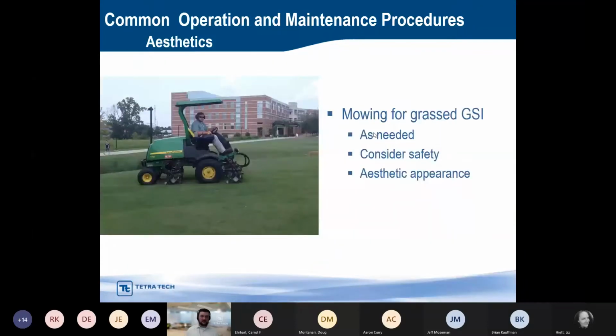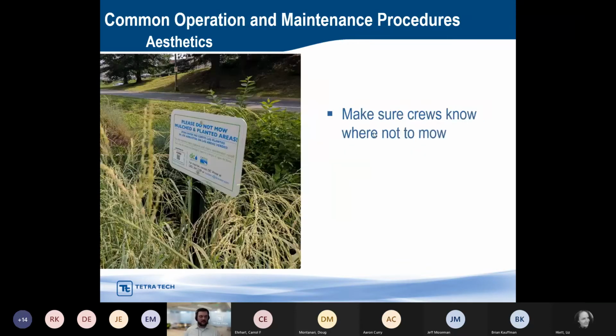So that's a big one. Again, if you have a BMP that's grass, we've seen several BMPs in previous presentations that are grass. Our detention basins and bioretention areas are often turf, and they function quite well from water quality and hydraulic standpoints. And so you're just going to continue mowing these just like you would if you were integrating a detention basin in a park somewhere. The maintenance for that is to continue mowing whenever it's needed. So again, it's an aesthetic issue first of all, but it also goes towards helping to maintain the function of that BMP. So if we're doing that, it's also important.